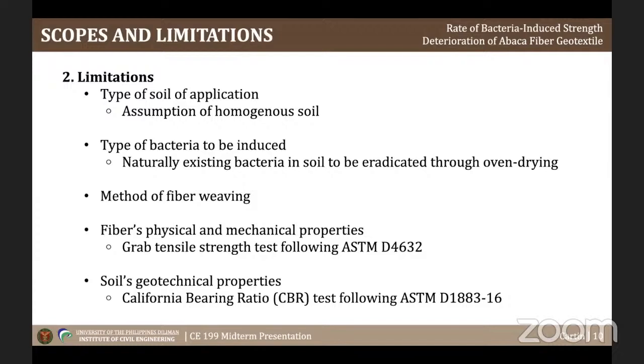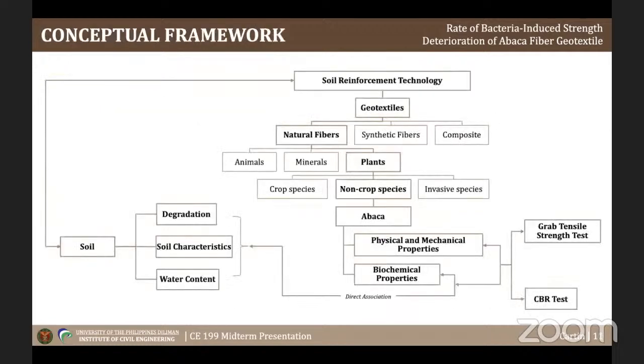The tests will also be limited to checking the tensile strength of the fibers using ASTM D4632, while the soil CBR test will be based on ASTM D1883. Abaca fiber geotextile as a soil reinforcement technology is the focus of the study. Specifically, the abaca fiber's properties and strength deterioration as it is subjected to natural forces in the soil, such as microorganisms, will be studied to assess its overall tensile strength.